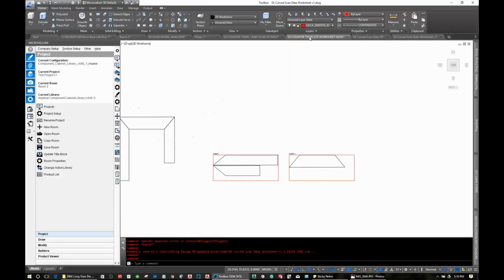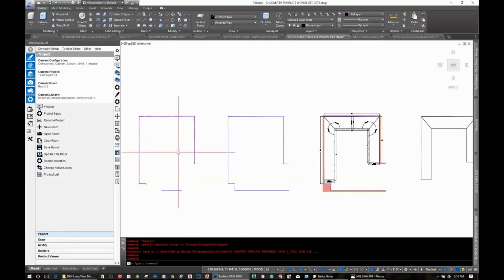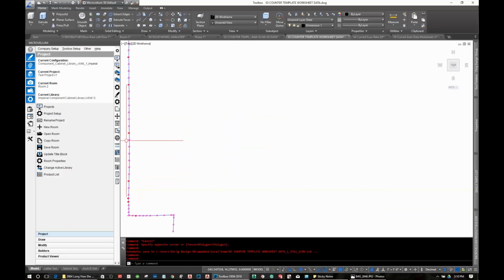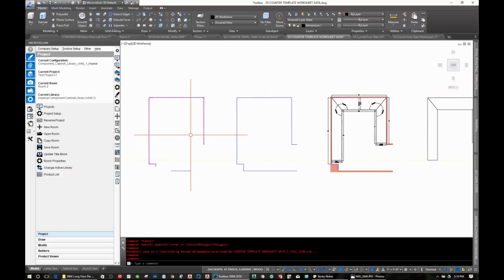So I'll jump into this one. This was just a simple countertop scan. I would say I was doing these about every inch and then half an inch in the quarters. I want to say it took about 20 minutes to do the scan. So I set up the laser. It has an automatic feature, and you just start in one point at a certain height, and it'll stay level at that height, which I went with 30 inches off the finished floor. And it scanned around the room. I made sure the file was okay and exported it, and I was out of there.